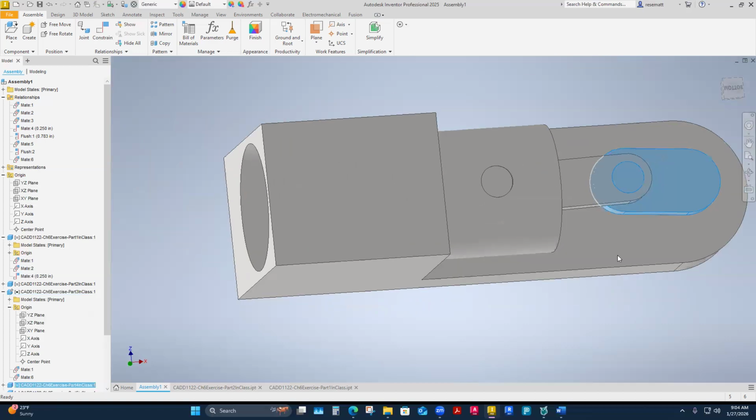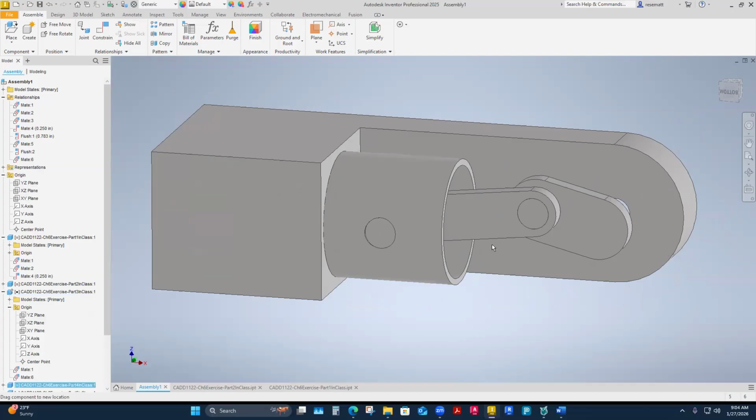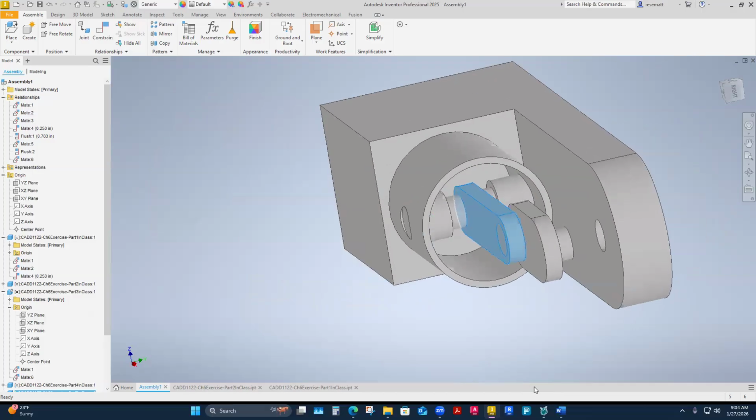So what they're showing is that this is not sufficiently going into my piston case far enough. So I've got an issue where this connection rod is too short. They pre-planned it to be too short. In my book, I think it says we need to extend that. Two and a quarter was our original hole to hole center on the part. They say, after evaluation, they need to put it out at 4 3/4 long.